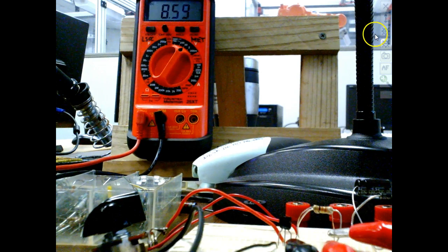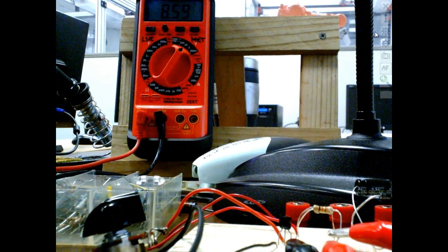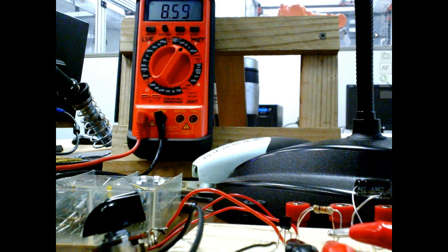So beta changes with what? Temperature. If beta changes and I don't do something, then my collector current's going to change. But saturated switches, we don't worry about it, because we use minimum beta. We saturate it at minimum beta. So if beta goes to 100, collector current can't change, because that resistor's already dropping all the voltage anyway, right? Okay? All right, y'all go to the lab now.